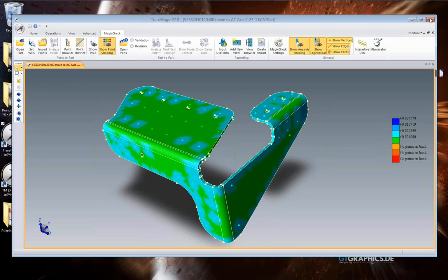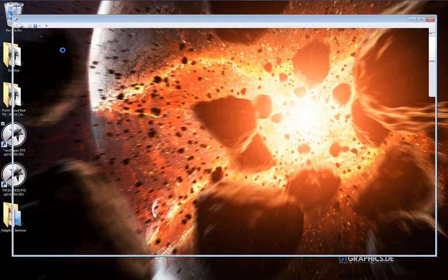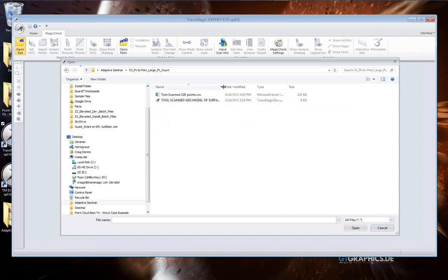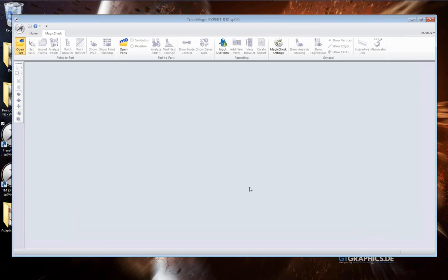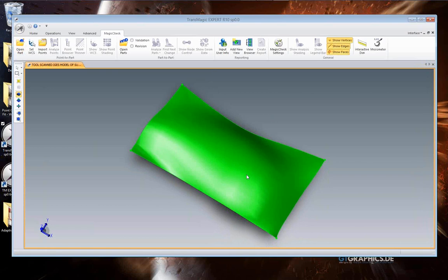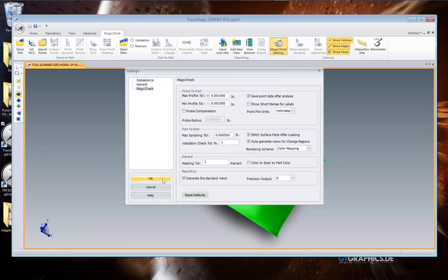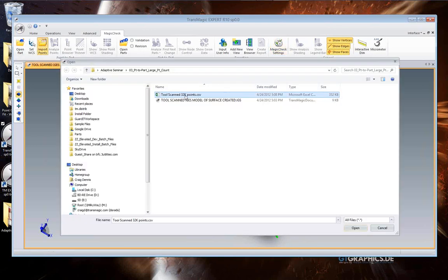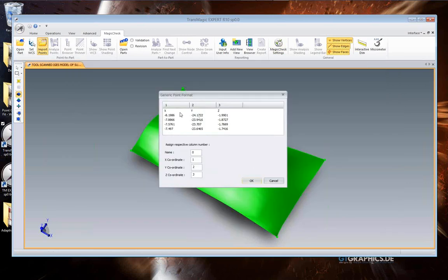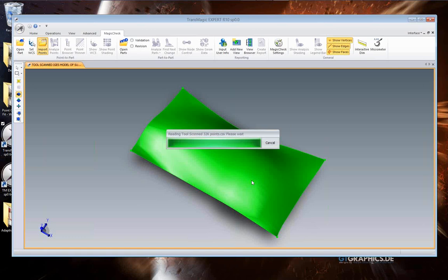So let's go to the next type of point, and this one is a more dense point set, more along the lines of, say, a laser scan. In this particular case, our source surface that we're bringing in is an IGES surface. So it's not going to have that coordinate system because that format doesn't support it. And again, I can't remember if these are inches or millimeters. I think they're millimeters, but we may need to re-import them because it's not included in this particular CSV file. In fact, this is all we see. So let's bring those in.